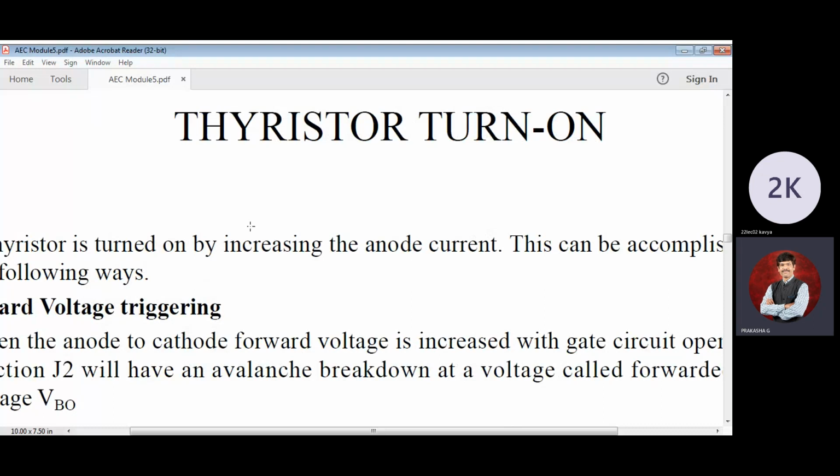That is what gate characteristics are. What are gate characteristics? You will be finding the IG, the VG, the IG minimum, the IG maximum. With respect to that, VG maximum, VG minimum, you are going to calculate. Then you will find the duty cycle of it. Duty cycle is basically calculated with respect to the pulse width of the gate towards the T on time. So pulse width T should be greater than T on time.